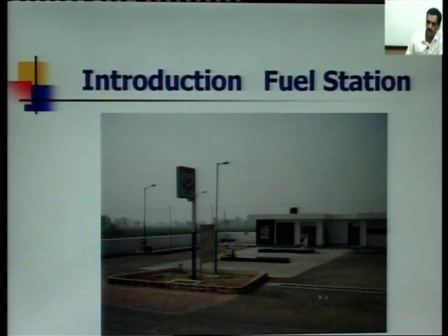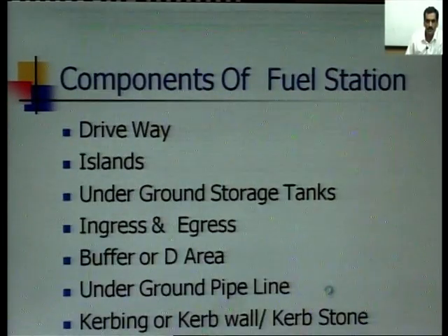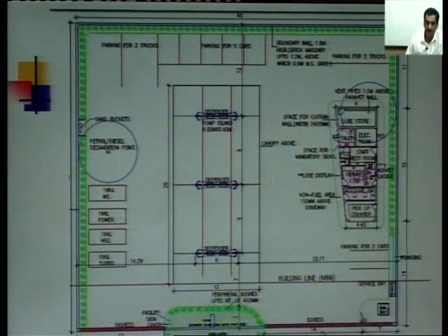If it's a rural or a smaller outlet or a city outlet, the section of this drain may vary from 1 feet 6 inches by 1 feet 6 inches to 2 feet by 2 feet. On this drain, we are having grating, and the entire water from this area is trapped into this drain. We are also going to have a back slope into this area. Back slope is the slope from the outer area, from the PWD area, and the slope from our main outlet.